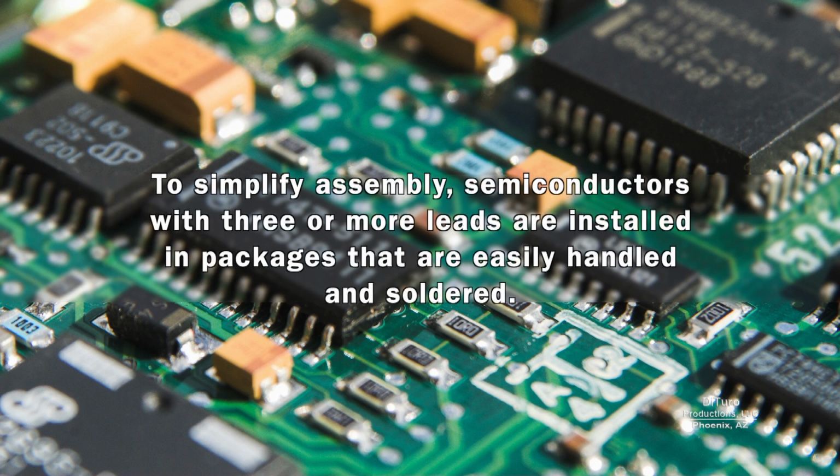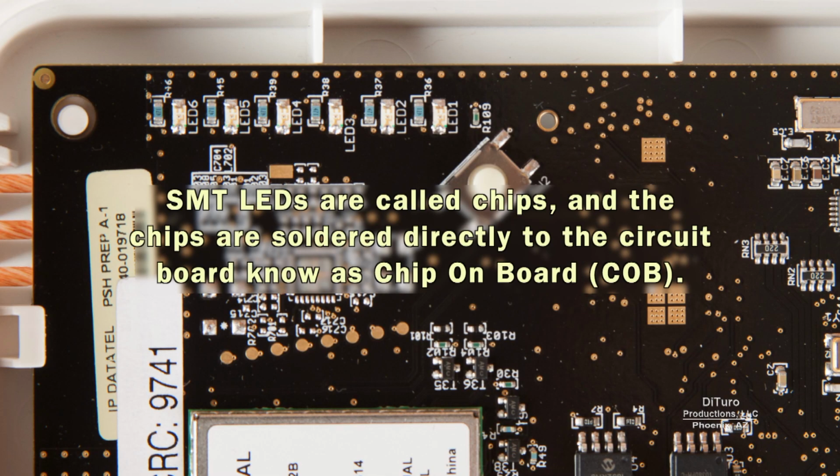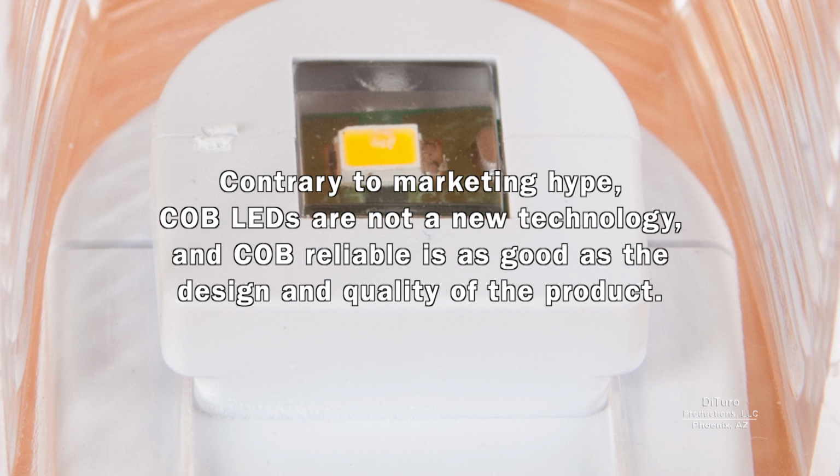To simplify assembly, semiconductors with 3 or more leads are installed in packages that are easily handled and soldered. SMT LEDs are called chips, and the chips are soldered directly to the circuit board, known as chip-on-board. Contrary to marketing hype, COB LEDs are not a new technology, and COB reliability is as good as the design and quality of the product.